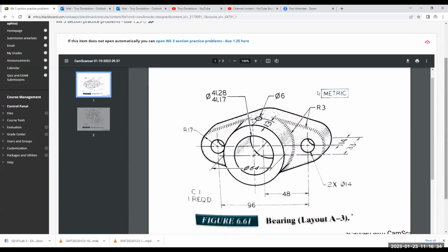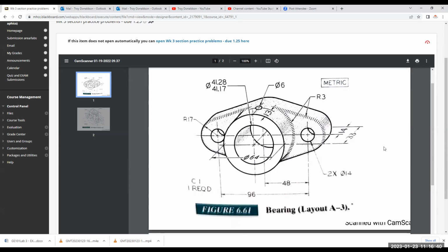Okay. All right. Any questions on this dimensioning? On this top one? Yep, it's in millimeters. Everyone knows what the 2 times means? Two locations is what that means. And so it's the two obvious locations that look the same. This one and this one. So notice this radius here, the 17, is to the outer curve, right? What about this one up here? What is that? It's diameter, yep.